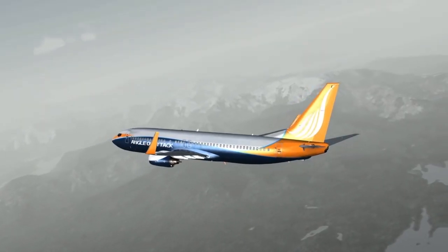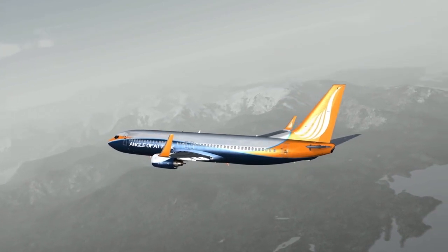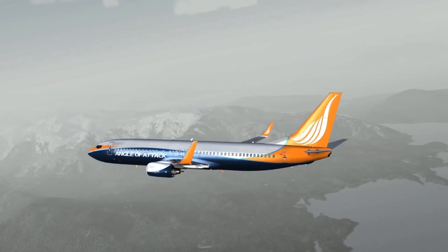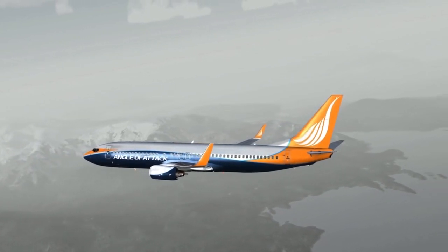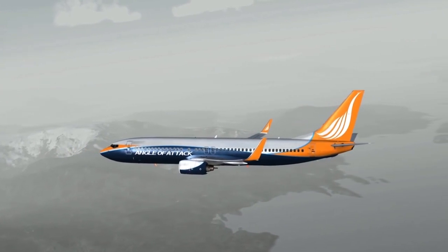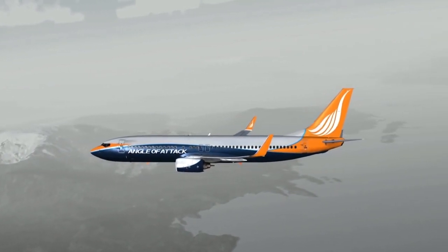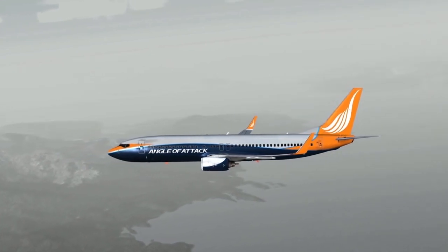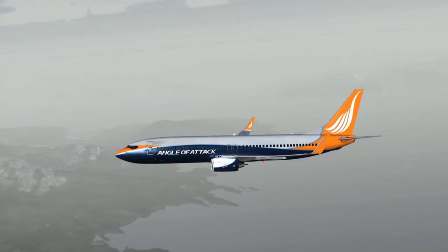The Mach trim system provides speed stability at Mach numbers above 0.615. Elevators are adjusted relative to stabilizer position as speed increases, subsequently changing the control column neutral position through the elevator feel and centering unit. The Mach information is obtained from the Air Data Inertial Reference Unit, or ADIRU.